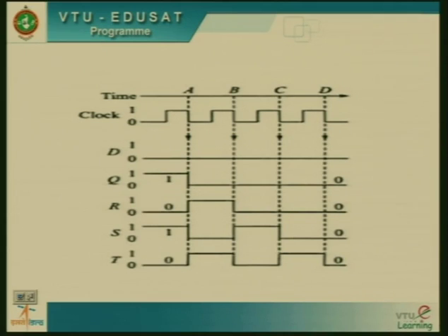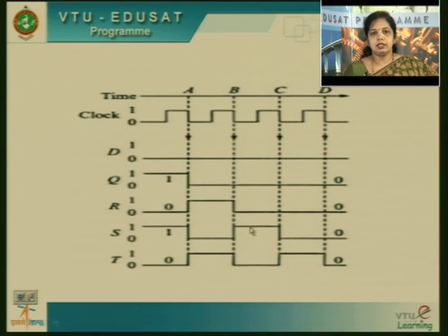If you apply the next clock pulse again, the last LSB part will be shifted out, or the data will be lost. You can just see here the clock timing. So Q1 is shifted here, next it is shifted here, next it is shifted here. After the 4 clock pulses, it is 0, it is lost. So I am transferring now 0 1 0 1. 1 has been shifted, next 0 is shifted, next 1 is shifted. So 4 clock pulses, 1 2 3 4, will complete this cycle.